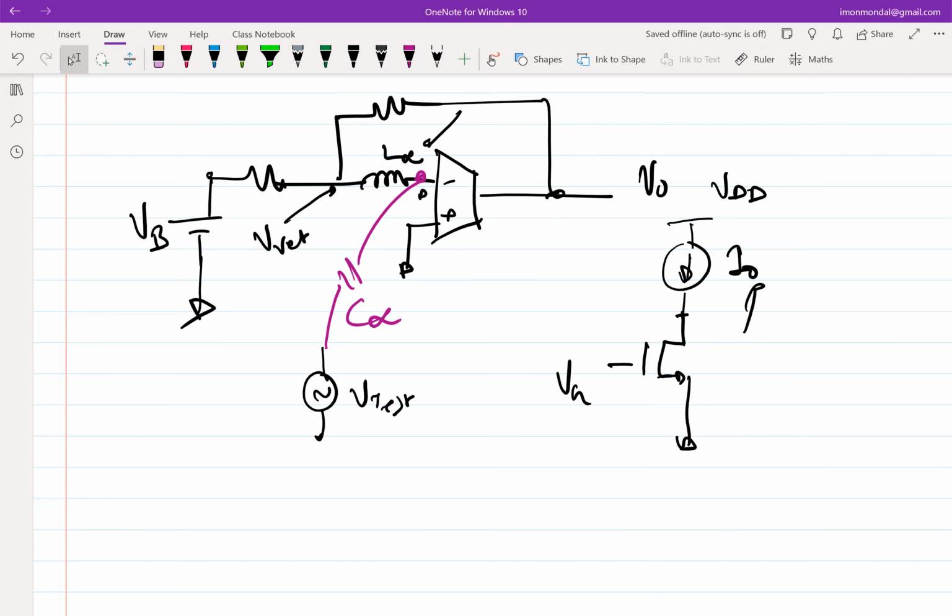So let me give you another way of thinking about it. Let's assume that you put this I0 and you have this VG. You automatically have this VG, right? What are you assuming? Pardon? Yeah, but how will you get that VG? You're assuming there is some way that information at the output is being fed back, that the information that I0 current is going out, that I am trying to sink, has to be sent. How will the gate know what is happening at the drain?